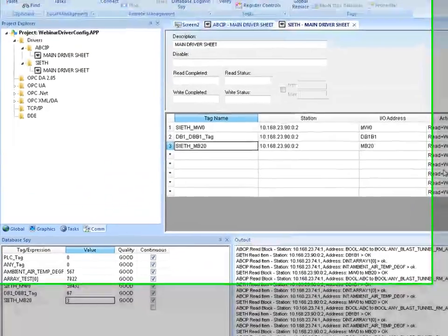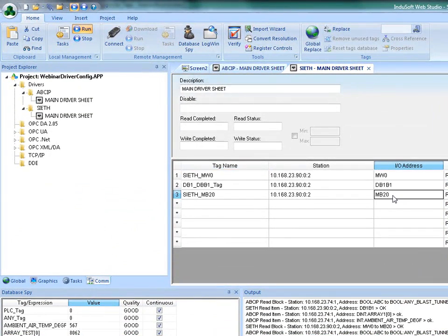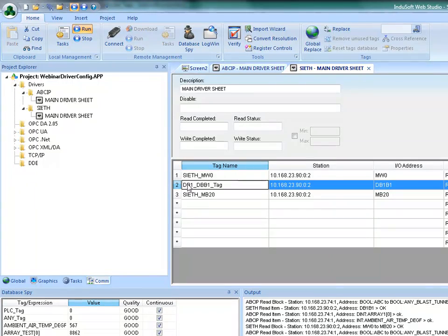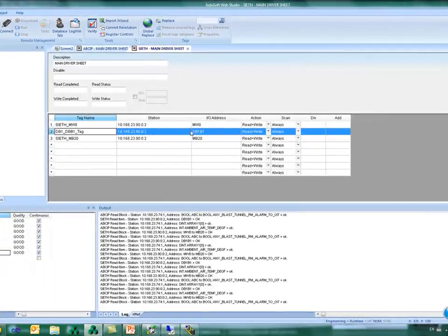the same message. Okay? So for Siemens, my hint is that you use DBs as much as possible, because you can fit a lot of DB positions on the same message. So the fewer DBs you use, the better the communication is going to be. Don't say, oh, Andre said we should use DBs, so I'm going to use 100 different DBs on the Siemens.